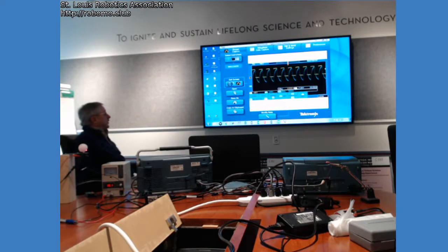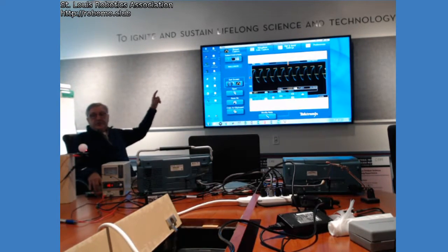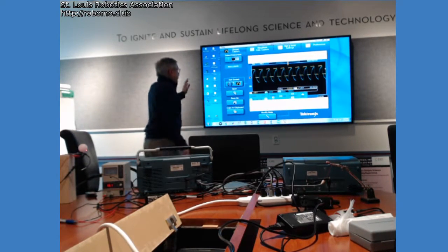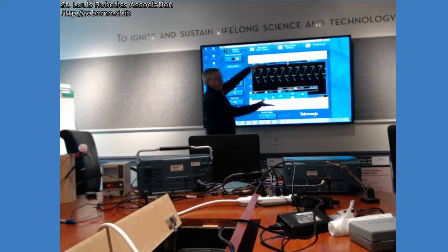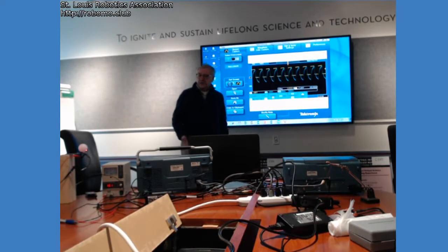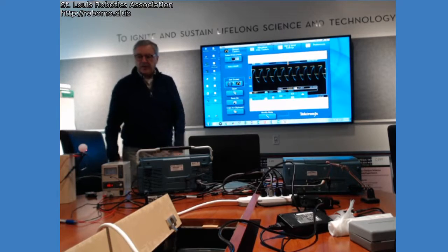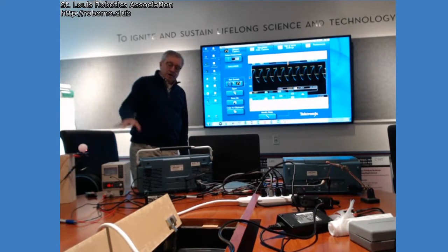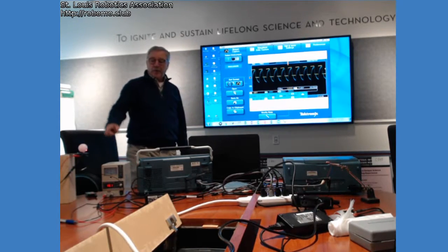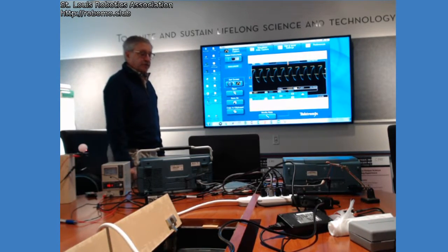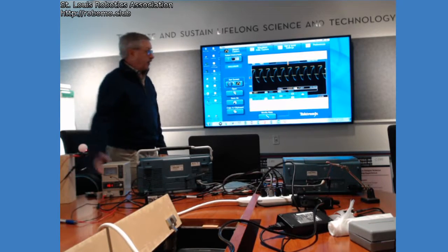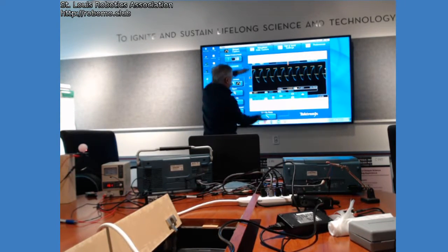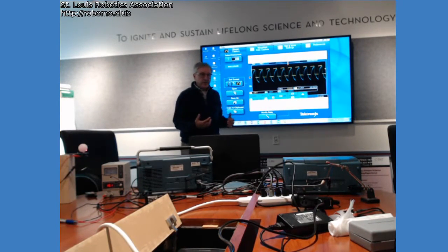Okay, we're back at 1 kilohertz, and you can see it's starting to. The RC time constant is such that it's now just about starting to lose some amplitude. So 1 kilohertz for this configuration might be about all she wrote. However, if you used a smaller resistor, say 100K instead of 1 meg, you'd have smaller amplitude, but he'd be hanging in there. He'd be looking good.